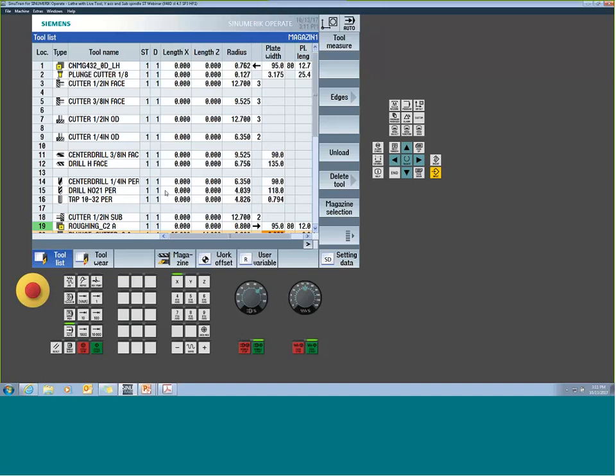In just about any of those FANUC controls, there's a machine parameter, and you can switch whether it's reading an A, B, or a C protocol. And if you don't know what you're used to, do a little digging. Go to your FANUC manual. You'll see that there's 3 different protocols. It has to do with what the threading cycle looks like. A 2-line G76 cycle came out in FANUC B. FANUC A used a different threading cycle. I don't know all the cycles because my shirt doesn't say FANUC.